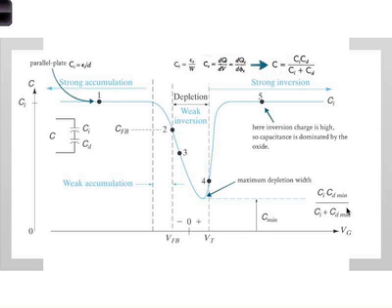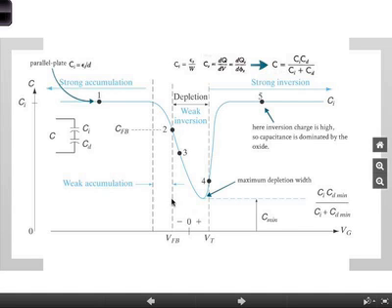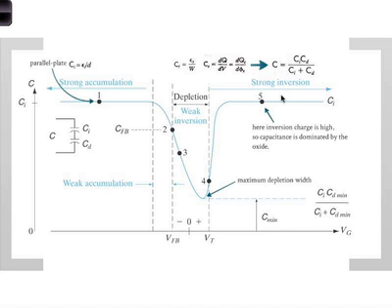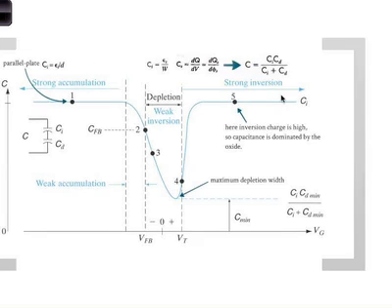Yes? What's the relationship between CS and CD? They are the same. Yeah. CS is more general in the sense that S stands for semiconductor, so capacitance of the semiconductor. D stands for depletion, CD. In most of the cases, the depletion region dominates, as over here. But over here, the depletion region has very little contribution. So over here, it's called CS because it's mostly the inversion channel. So this number gets really large, essentially, and you ignore it in the total equivalent circuit. Okay, so that's a quantitative picture, okay?